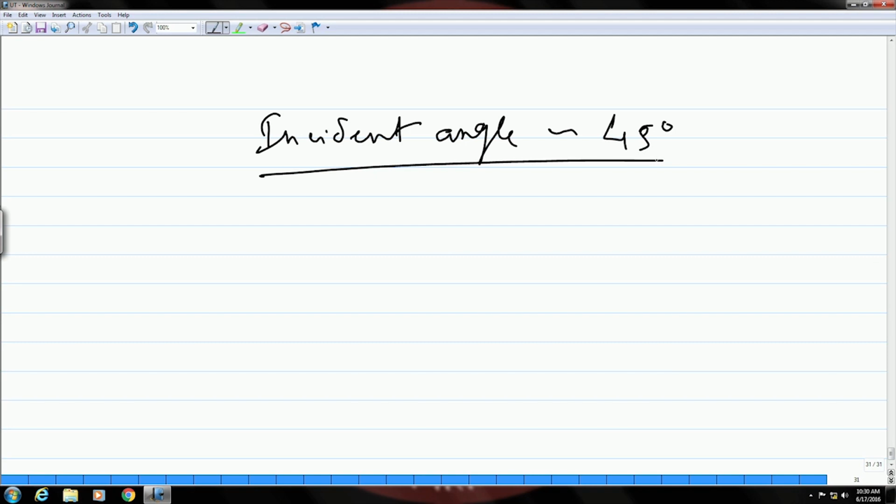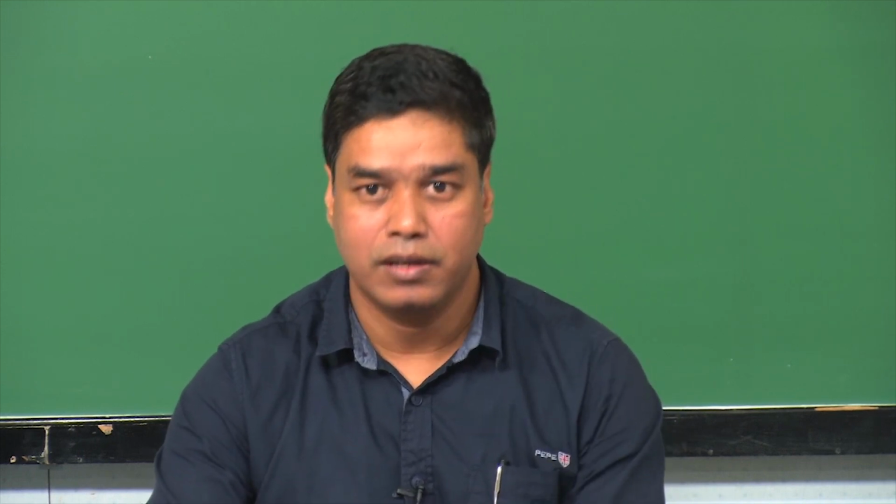Okay. So, this will ensure that shear waves are only entering the sample and the whole sample will be inspected by these shear waves. Okay. So, this is how, when you do the inspection using angle probes, you choose the angle depending on the velocity of sound waves in the material that the sample is made of.